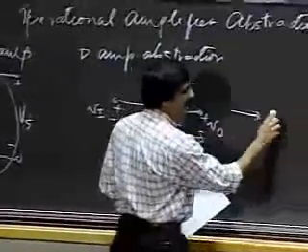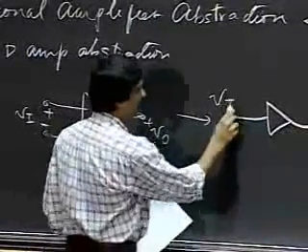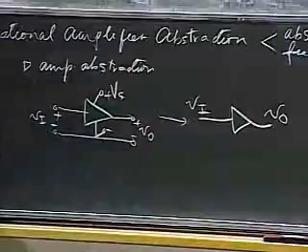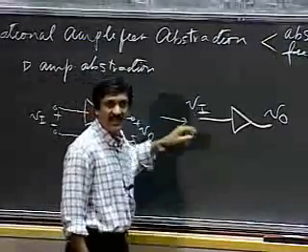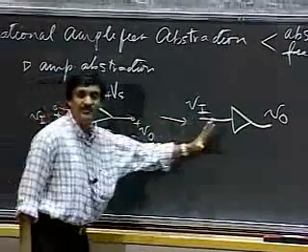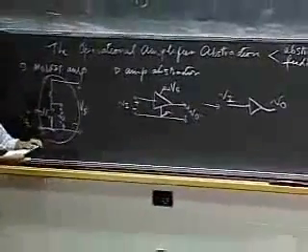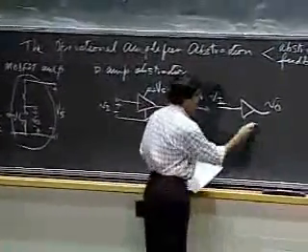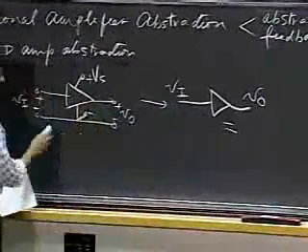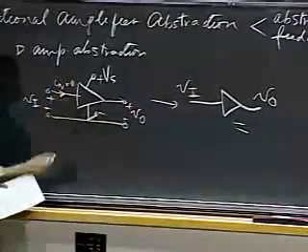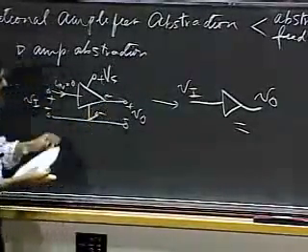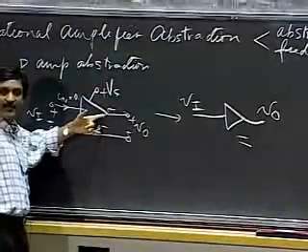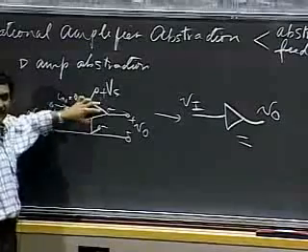And an even simpler version of this for many applications might just look like this. VI and VO, where there is a ground that is shared among them that's implicit in this picture. And VI and VO can simply be the node voltages at these nodes. So this is a progressively more abstract representation of this amplifier. So what we can do is, provided we know, we can abstract out the relevant properties of this block and expose them outside. And the relevant properties might well be that, let's say here, I in is always 0, all right? I can also express to you the gain of this amplifier. I may also be able to tell you a Thevenin equivalent for the output. Okay, so there are some properties that I can give you that will let you use this building block abstractly.